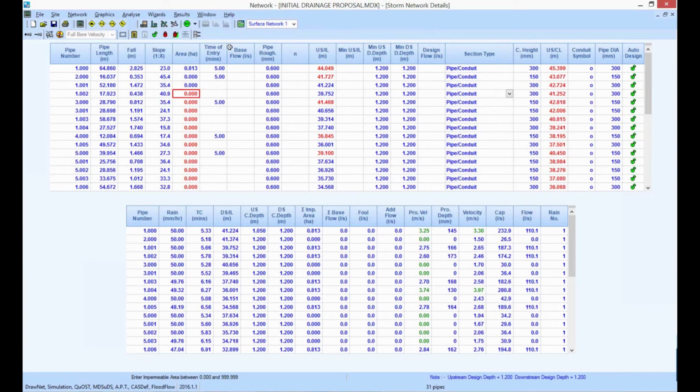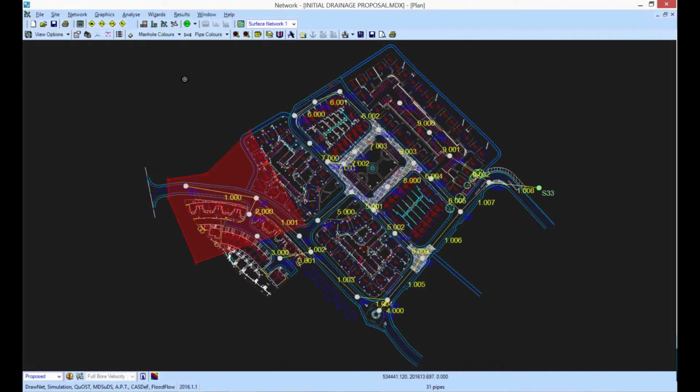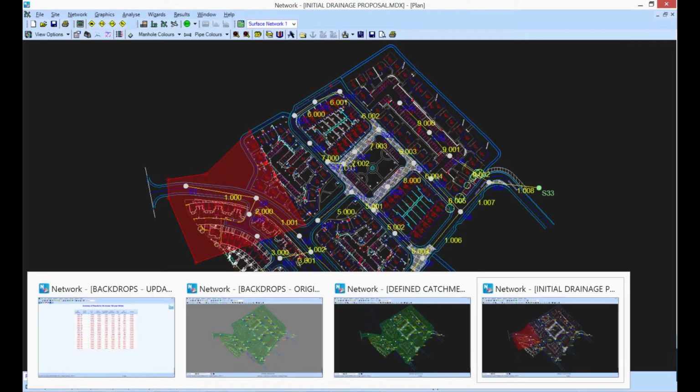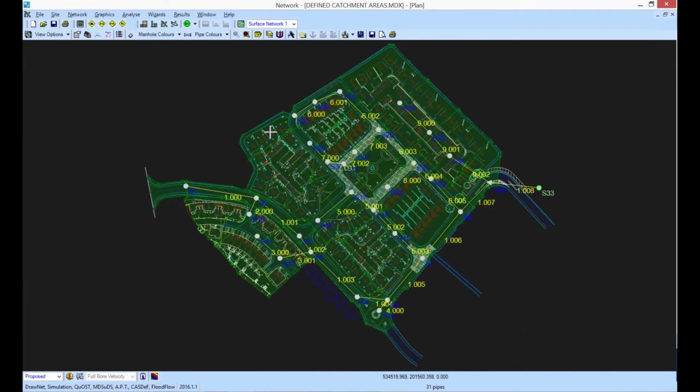So all it is now is a case of me going around looking at the topography in the plan view and identifying those subcatchments and assigning them to the manholes. So that's a nice, quick, easy job. I don't have to redefine the pipe network because that's been done by Dan. So in true Blue Peter fashion, here's one I've done earlier. So I've fully defined my site extents now, draining into my drainage network.